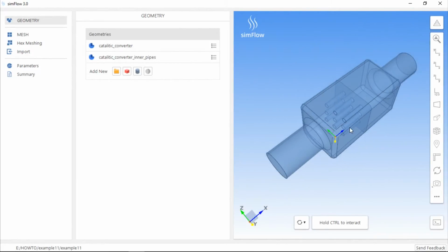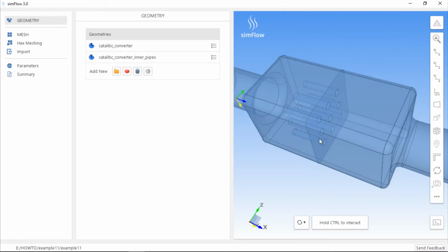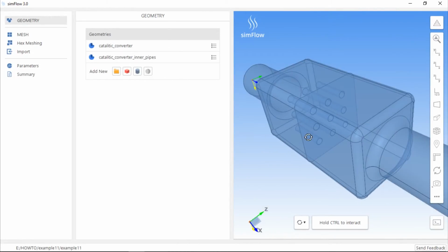The fluid will flow from the inlet pipe, enter the pipes mounted to the plate and flow farther downstream, towards the outlet pipe. It's worth noting that the fluid will be present on both sides of the plate and small pipes. Therefore, in order to simulate this case, we need to create baffles. Baffles in SIMFLOW can be created during mesh generation.